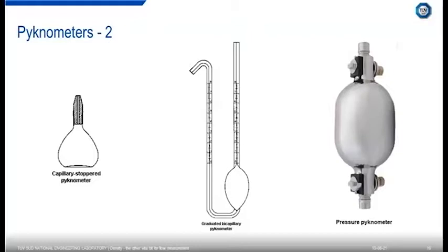The capillary stopper allows you to do that because when you overfill the vessel, then put the capillary stopper in, it flows back out to the top of the capillary, and you have a known volume consistently every time. You measure the weight of the empty vessel, then the weight with the fluid whose density you are determining. You've calibrated the volume with water, you've got a mass, a volume, you've got a density.